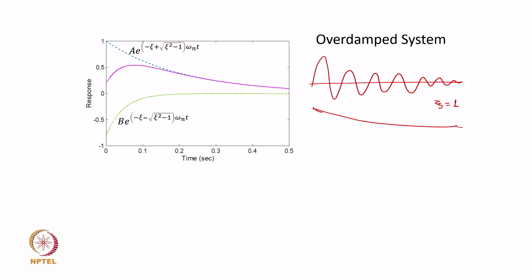Okay. For example, the door closer mechanism that you have, you would not like the door to be swinging back and forth from its equilibrium position once somebody pushes it outwards. Those oscillations are irritating, and no designer would like to have a very low damping for a door closer, but at the same time you would also appreciate that if the door closes after too long a period of time, it loses its meaning, because one has to wait for a long time for the door to get closed.